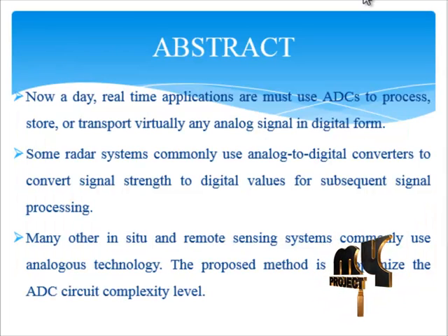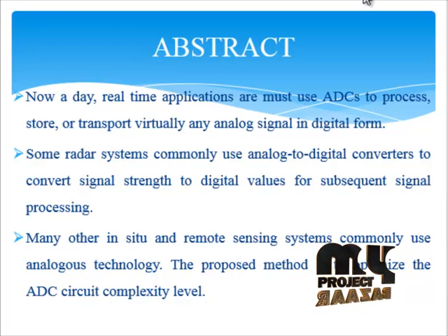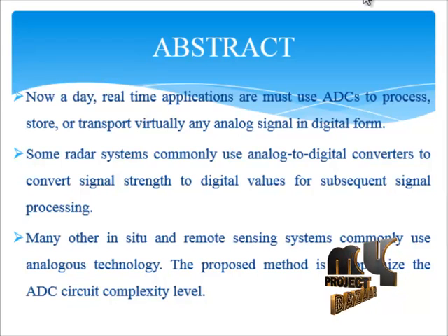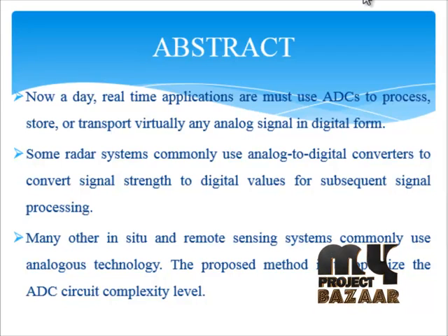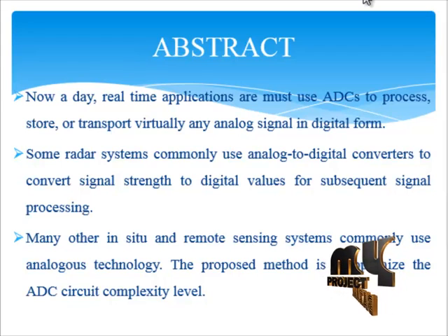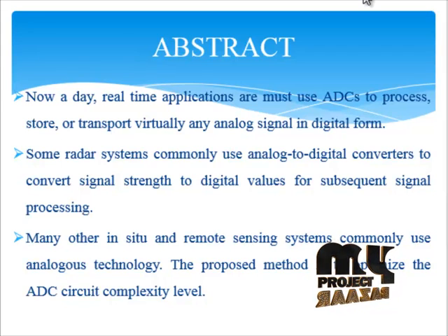Let's see our product abstract. The ADC implemented in our process is measured under different input frequencies with a sampling rate of 250 MSPS, and it consumes 300 milliwatts from a 1.8 volt supply. For the 30 MHz input, the measured SFDR and SNDR of the ADC are reported.